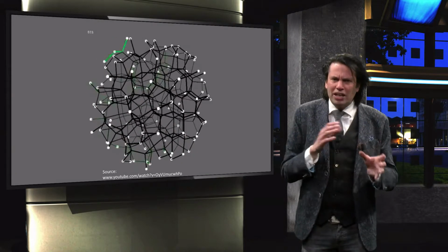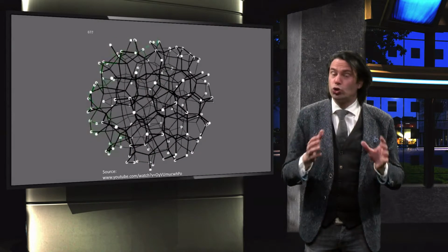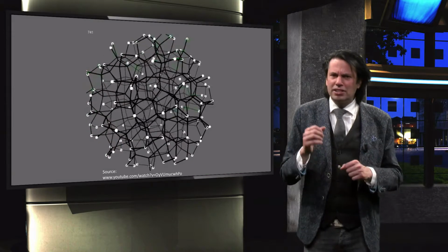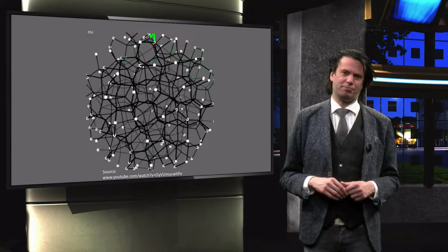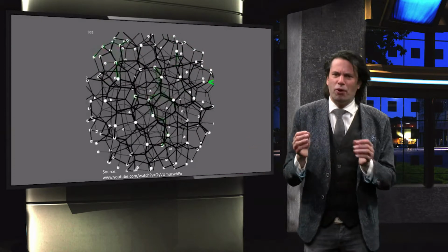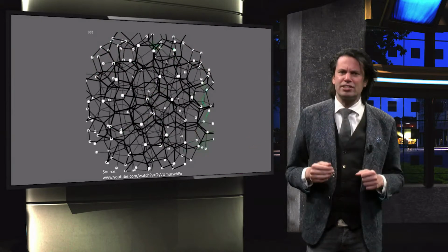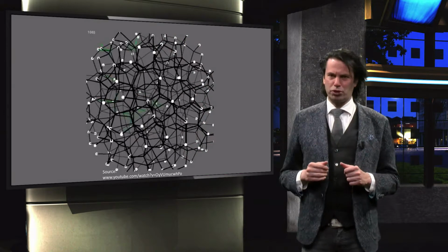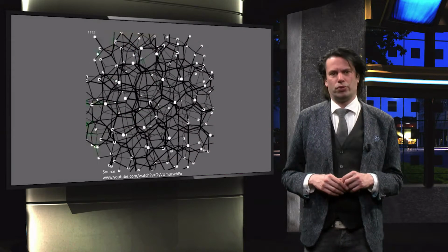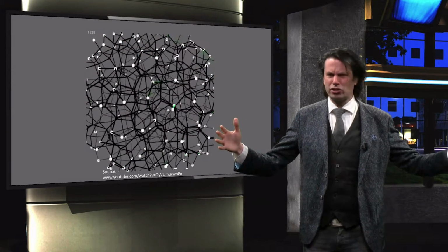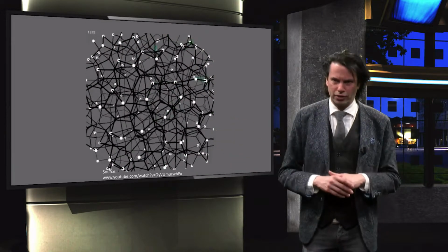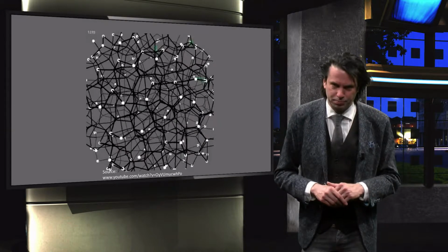On atomic length scales, or what is called short-range order, the atoms still have a tetrahedral coordination structure, just like crystalline silicon. But the silicon bond angles and the silicon bond lengths are slightly distorted with respect to a crystalline silicon network. Therefore, at long-range orders, the lattice is no longer like crystalline silicon lattice.